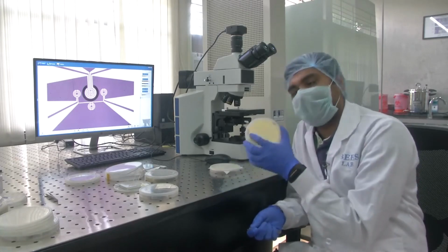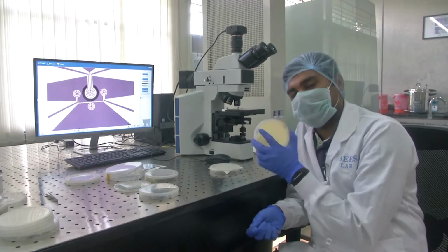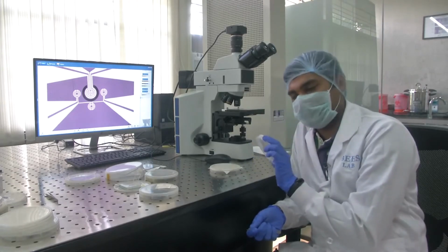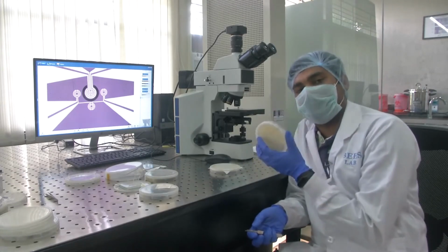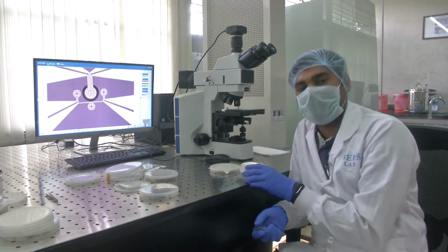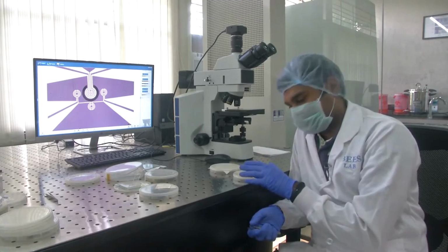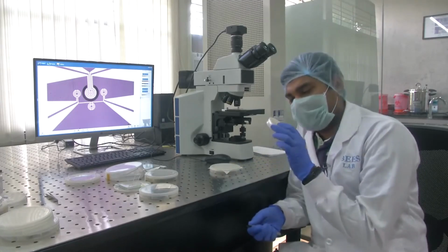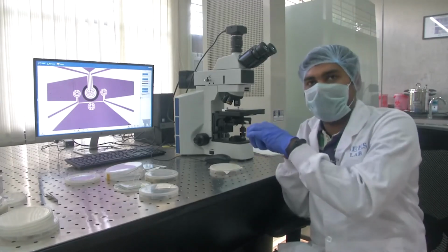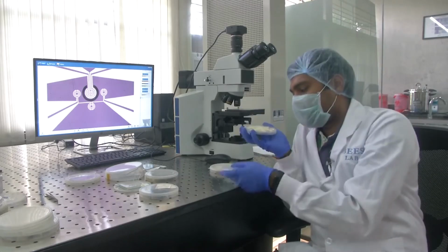You should always carry your devices or wafers in wafer carriers for contamination purposes and also for safety of the wafer, so that it doesn't break. These are all expensive materials, and it should not break. So it should be carried in wafer carriers also all the time. So let me open it for you. So I am opening it.